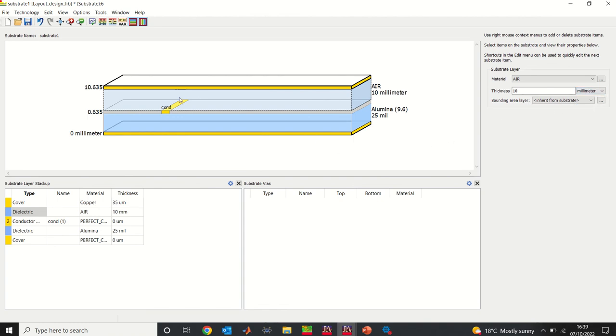So you need to have that space of 10 millimeters for optimum simulation. It doesn't have to be 10, but to get optimum simulation, I encourage you to use 10 millimeters. Now, once I've done that setting, that's fine. The next thing, I'm just going from top to bottom.